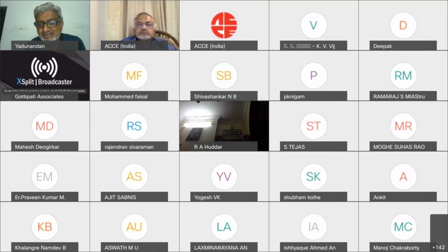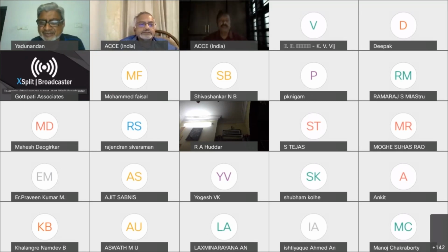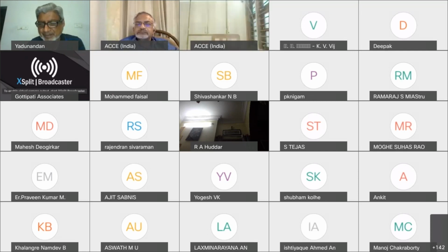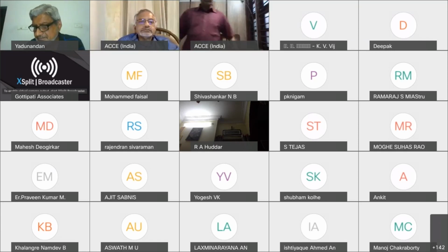Sometimes if you have a very high multi-story structure and you don't have shear walls and other things to interact, it is possible that you may need a larger concrete section with a restraint of the maximum percentage of reinforcement. You may have to provide thicker columns. That depends on the situation. So by providing a little increased percentage of reinforcement, we can also try. That's what you're saying.